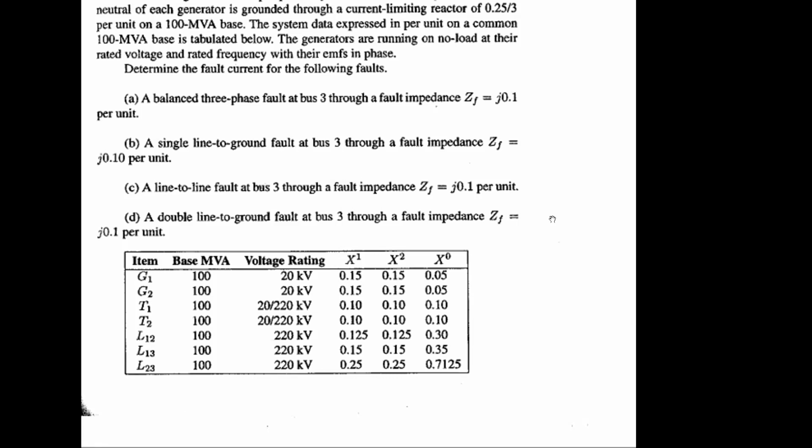First of all, if you have been given any single line diagram, can you address the fault current? Yes sir, we have to start with Thevenin. First, we have to find the Z equivalent using the Thevenin theorem, the Z equivalent for 3 different scenarios. Okay, that means Z0, Z1, Z2. Yes, sir. And when you use Z0, be careful about the transformer zero sequence circuit.